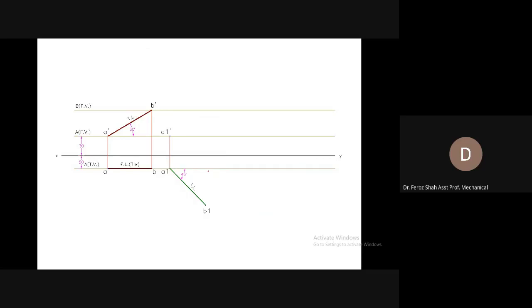As this locus line is parallel to the XY reference line, you can use this as a reference as well. So with the protractor, measure this angle of 45 degree, start from here and draw a line of 80 mm. That would end at this position. Name it as end B. As in this step, you have given it the annotation A1, B1, this end would be called B1.